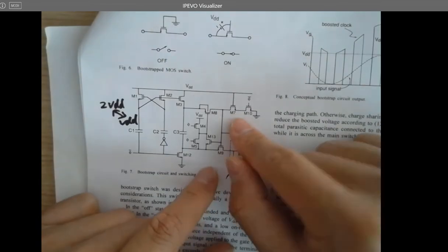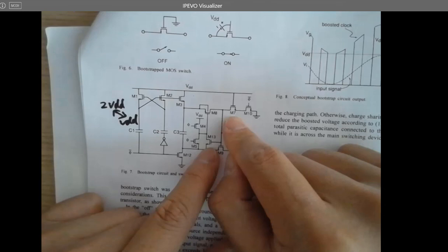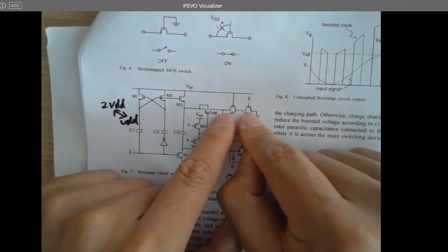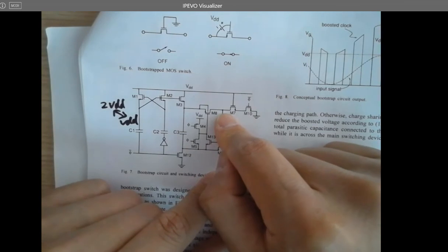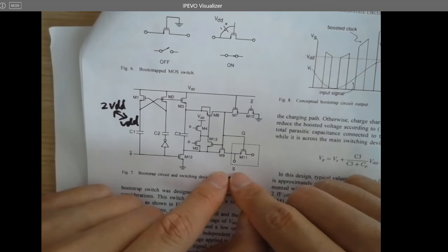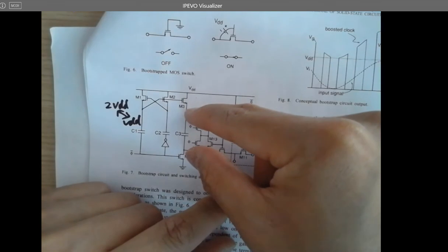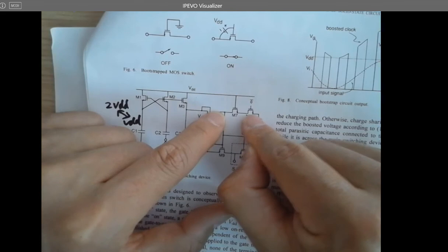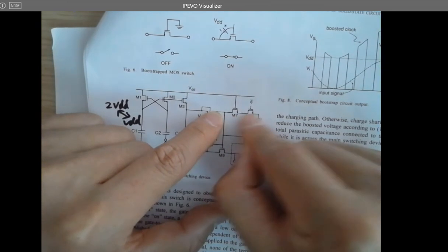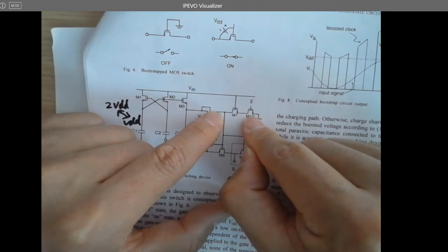So there's a question regarding this one. What's the function of this NMOS to be here? It's always on. So why would you want to add one NMOS in the middle of these two parts? Because this voltage can be higher than VDD, sometimes 2 VDD. If the input signal for the data is VDD, then this VDD will be added to the previously stored VDD here, so the voltage here will become 2 VDD. And 2 VDD being added to the drain of this transistor probably can blow up this transistor and burn it. So that's why you add another one to increase the resistance and have another voltage drop across this NMOS channel, so you can protect this transistor. That's the function of this guy.